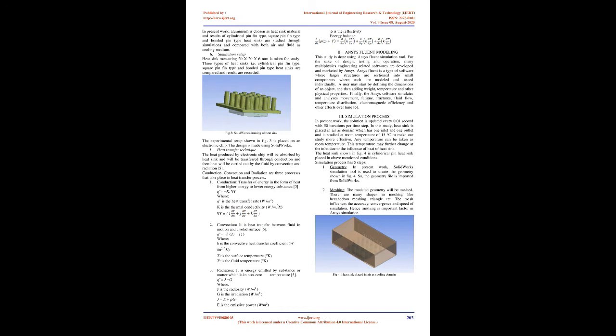5.2. Bonded fin type heat sinks. This type of heat sink is made up of an aluminium or copper plate first and then combined with a heat sink with grooves. One advantage in this type of heat sink is that different materials can be used for plate and fins. Heat dissipation ability is good. The main disadvantage is that it provides less surface area for cooling and is costly.